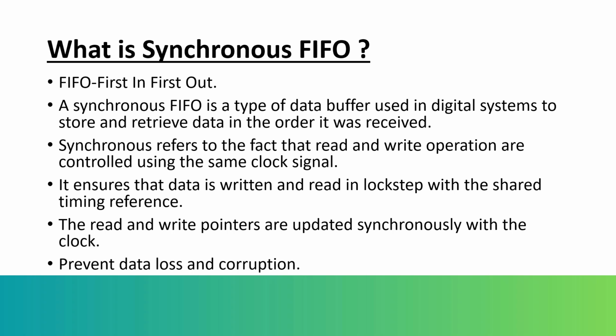And here comes the main agenda, synchronous FIFO. A synchronous FIFO is a type of data buffer used in digital systems to store and retrieve data in the order it was received. Synchronous refers to the fact that read and write operations are controlled using the same clock signal. It ensures that data is written and read in lockstep with shared timing references. The read and write pointers are updated synchronously with the clock, which is particularly crucial in high-speed systems where timing violations can lead to data loss and data corruption.